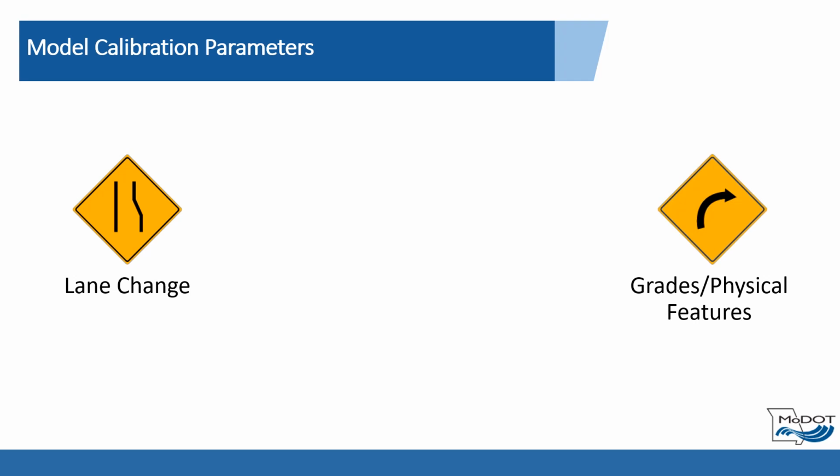Driver behavior model changes can be made to fine-tune traffic flow on freeway and arterial facilities to vary the aggressiveness of individual vehicle interactions and, ultimately, affect the capacity and throughput of vehicles along individual network links and connectors. Driver behavior adjustments and valid ranges of values to change in the calibration process are found in the Vissim Calibration Parameters Guidance in EPG 905.3.